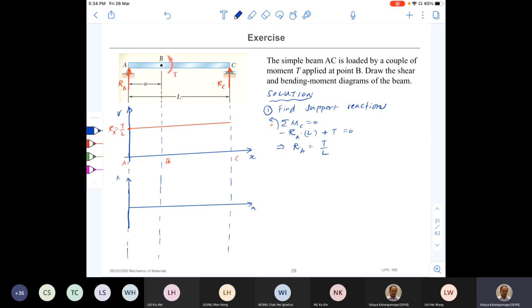X, and this way it is M. In order to construct the bending moment diagram, we need the area under the shear force diagram and also known values of bending moment at key points. And here at point A, what is the bending moment? At A, bending moment MA is equal to 0, so there's no bending moment. The starting point here is 0.